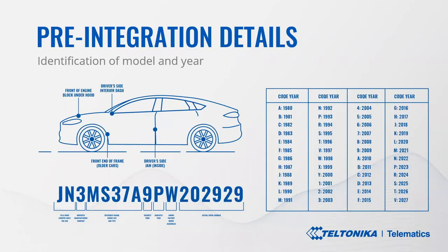So the VIN number, of course, consists of 17 symbols. The 10th symbol presents the manufacture year. Basically, according to the symbol provided in the 10th place, you can determine the make year, but please take into consideration that there are repeated characters in the table, and to fully confirm the make year, you have to make sure to follow position 7 of the VIN number.